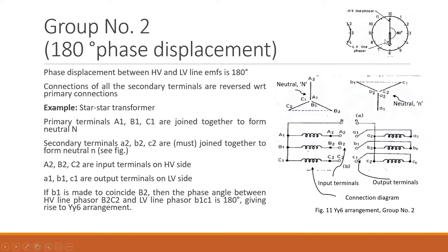In this case, what you need to do is reverse the connection of all secondary terminals with respect to the primary connection.